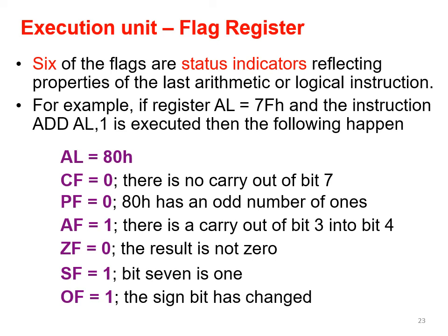7F plus 1 is 80H. Has it created any carry? No, it's perfectly well inside the AL, so you have carry flag equal to 0. Just count the number of ones here. For 8 it is 1000, there is only 1 there, and then again 000, no ones.